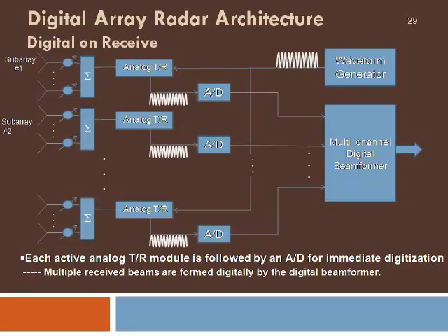So here we have the signal combiners of 2 or 3 or multiple antennas. The output of these signal combiners will be an analog signal, which will be processed, that means basically filtered and amplified to a sufficient level initially. Then the signals will be converted into digital form. So all these digital signals from different sub-arrays will be combined in a digital combiner for further processing.